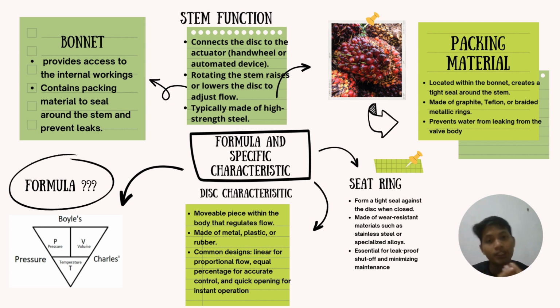Okay, so the stem function. Stem function connects the disc to the actuator, handwheel, or automated device. Rotating the stem raises or lowers the disc to adjust flow. It is typically made of strong steel. So, the stem function is more or less like a tool that drives the globe valve, and it connects with the actuator.